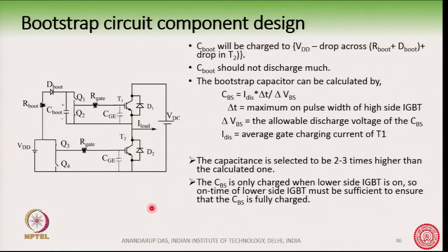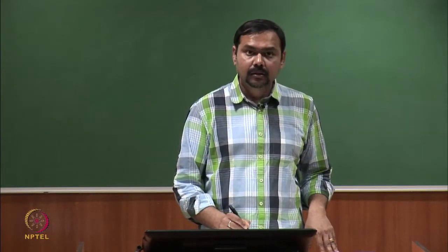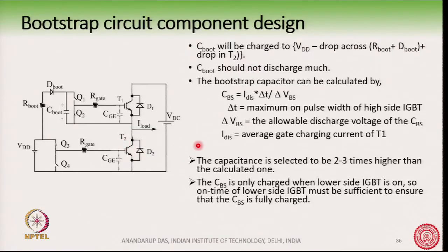In fact, for many such bootstrap circuits, the first pulse should be on the lower IGBT, because when it is turning on, C boot may be fully discharged.